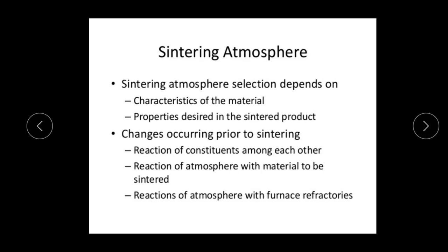Now coming to the next concept, the sintering atmosphere, which is very important. The sintering atmosphere selection depends on the characteristics of the material, the property desired in the sintered product, and changes occurring prior to sintering, which are the reaction of constituents among each other, the reaction of the atmosphere with the material to be sintered, the reaction of the atmosphere with the surface, and with the furnace refractories.